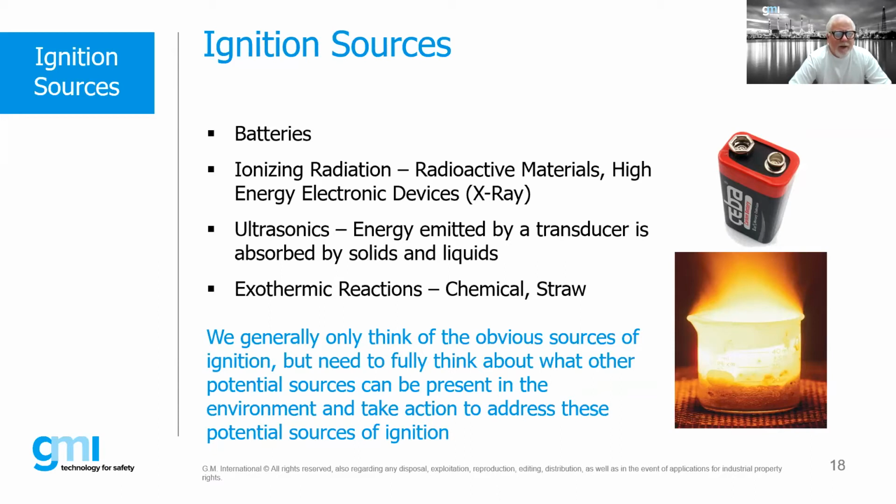But exothermic reactions are actually one of those things that can generate, just from the chemical reaction itself, a breakdown of the product itself, and then all of a sudden it can create an ignition source. And in the case of, again, ammonium nitrate, it can have devastating results. So we have to take all of that into account when we're doing our hazardous equipment or HAZOP analysis and trying to determine what exactly we need to do to address it.